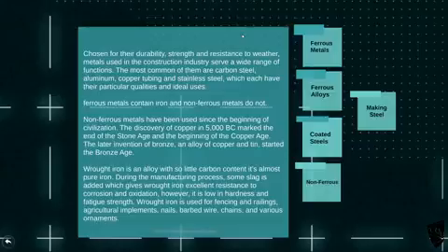During the manufacturing process, things can be added to it to change its properties. So you've got slag added, which gives wrought iron resistance to corrosion, which it doesn't normally have on its own. Oxidation, corrosion, similar. But it's not very hard, and as I said, fatigue strength is low. You'll find wrought iron used for fences, railings. Occasionally, in the old days, nails and barbed wire, but not so much anymore. So look around at old Victorian type properties and you'll probably see some wrought iron going around there.